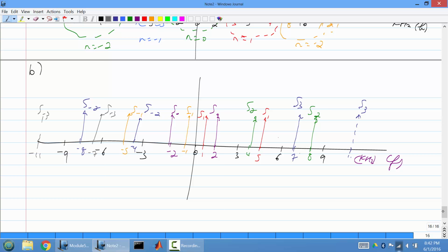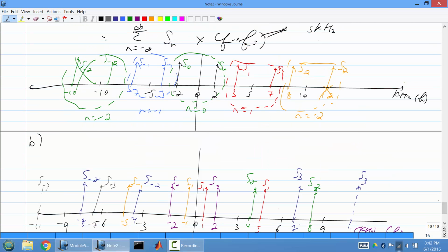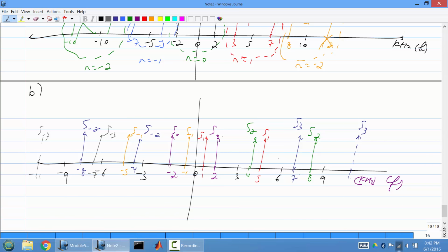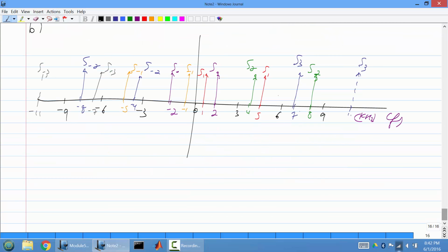So you can see that in comparison to the top, the spectrums are evenly spaced out. With the aliasing, what's happening here is that they kind of mix with each other. So if you wanted to successfully get your original signal back, you want to get these two impulses at minus and plus 2, but there's also minus 1 and plus 1 that's interfering with things. So you won't be able to get your original message back, unfortunately.